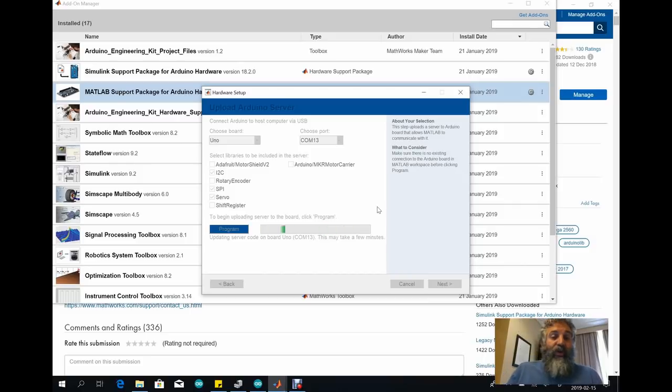So once this program is running on it, you will see how the TX RX lights are blinking all the time, because the computer will be sending requests to the board, which acts as a server, and it will be sending data back. So at every request there will be handshakes and data exchanges, and so forth, and that will make the lights blink all the time. Nevertheless, it doesn't mean that the thing is not working. It's the opposite. It means that the thing is working really well.